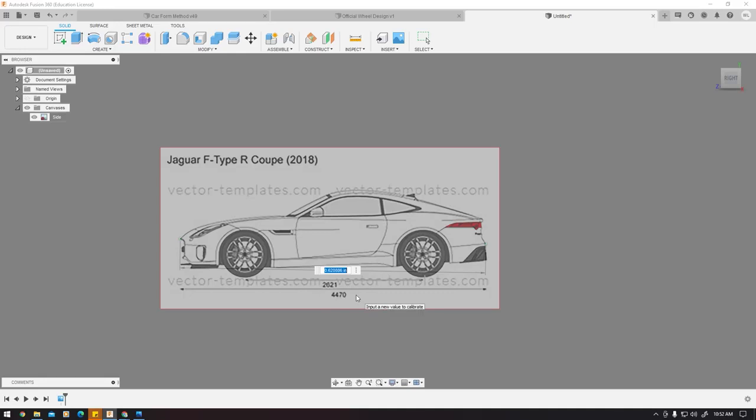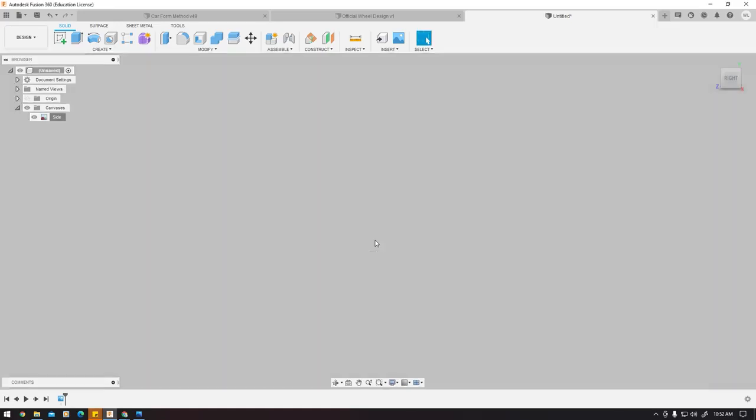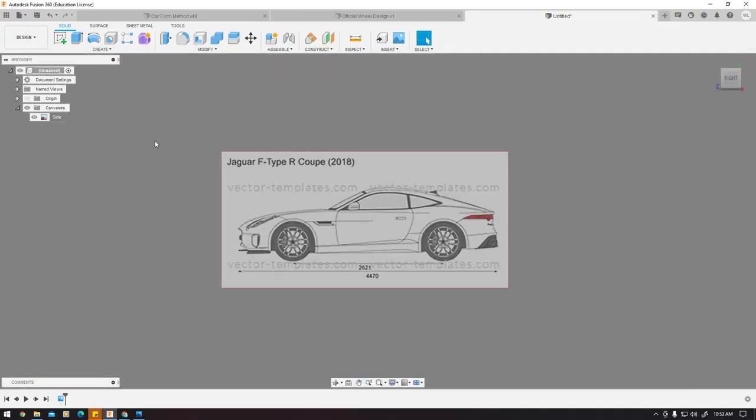This image is in millimeters, and right now our file is in inches, but an easy way to fix that is if you just type in 447 and a space and 2 M's, which will indicate millimeters. Press enter and it will be displayed as millimeters.